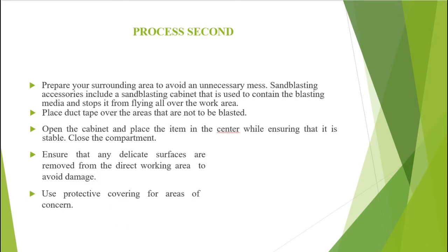Second process. Prepare your surrounding area to avoid unnecessary mess. Sandblasting accessories include a sandblasting cabinet that is used to contain the blasting media and stop it from flying over the work area. Place duct tape over the areas that are not to be sandblasted.